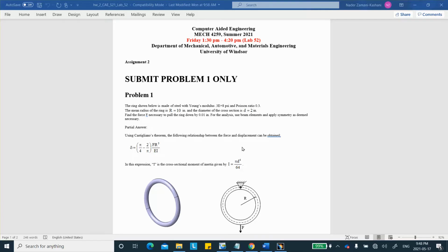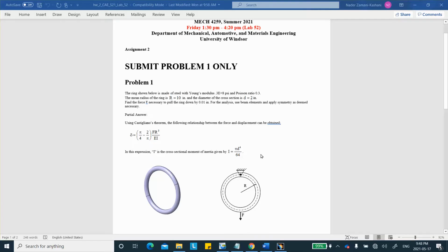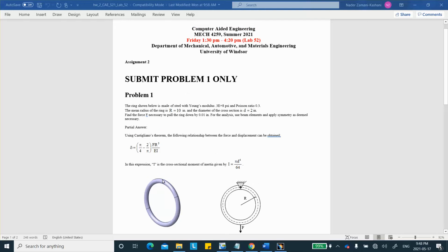Now, the second thing is that there are two ways to proceed. You know that you have to model half of this. If that is the case, you have two choices. You can draw half of this as a sketch, join it, and then proceed, or you can draw half a circle in space, which is a wireframe, and then proceed. I don't think you need joining there, but we're going to find out.